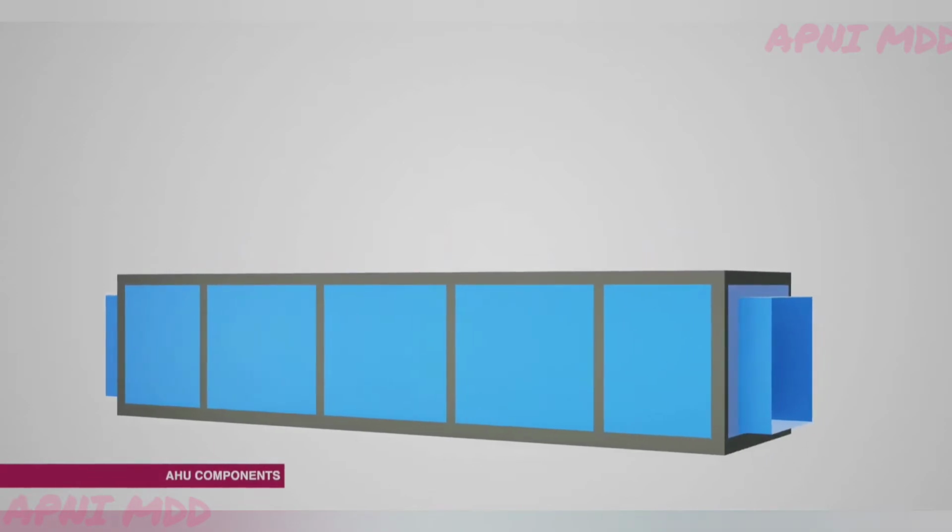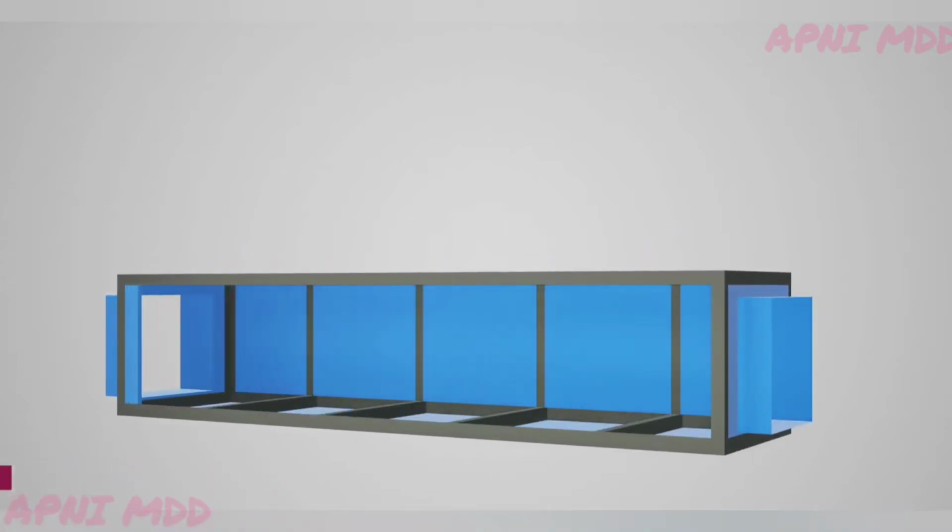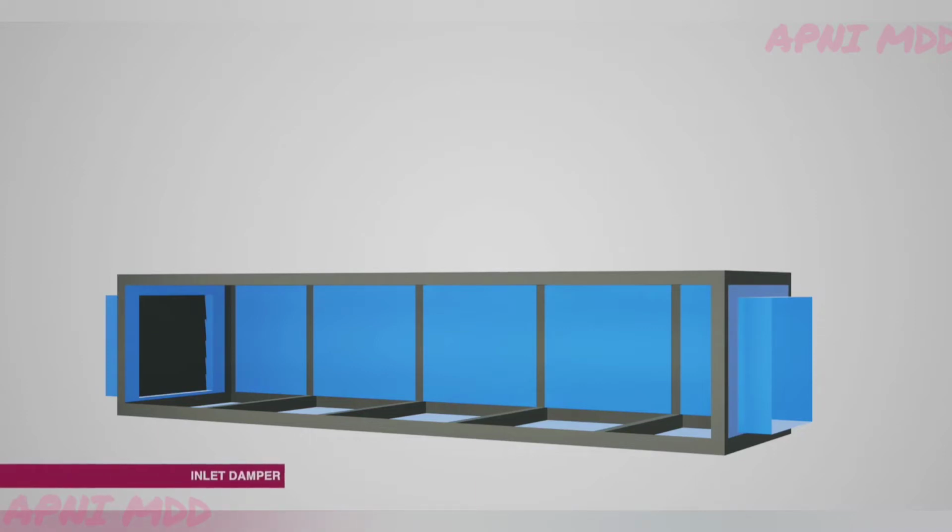Let's look into some of the AHU components. AHU itself is a large metal box with the following components. The first component of the AHU is the inlet dampers. This damper acts as a separating device between the air intake duct and the AHU. In order to provide clean and dust-free air to the building occupants, air filtration is always provided in the AHUs. Filtration is typically placed first in the AHU to keep all the downstream components clean.